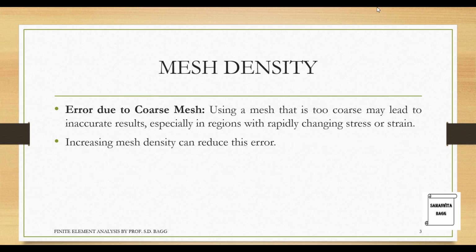First is due to mesh density, error due to coarse mesh. Using a mesh that is too coarse may lead to inaccurate results, especially in regions with rapidly changing stress or strain. Increasing mesh density can reduce this error.